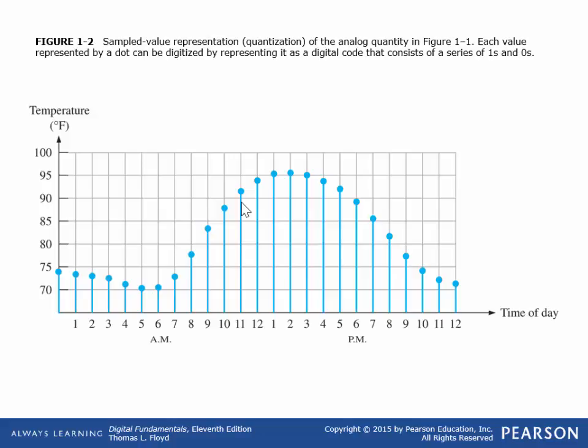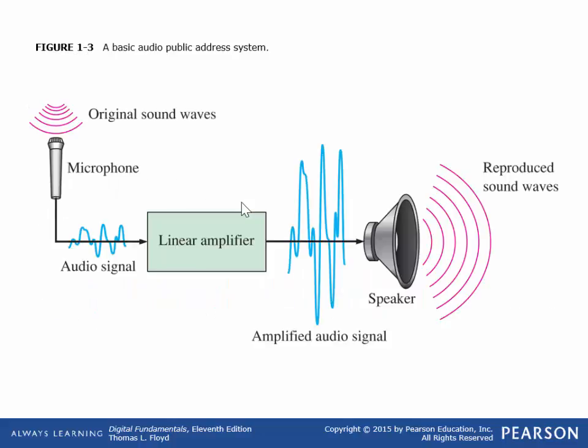There's a theory in sampling music or sampling anything that says as long as you filter everything past half of the sampling rate, you can restore it back close enough. Now, music we're saying is 44 kilohertz. Something like a telephone's 3 kilohertz. The sampling rate is 8 kilohertz. They sample at 44 kilohertz. They low pass filter down to 3 kilohertz. Music you low pass filter down to 20 kilohertz. We're not going to do much of that discussion in this class. It's just kind of what's going on here.